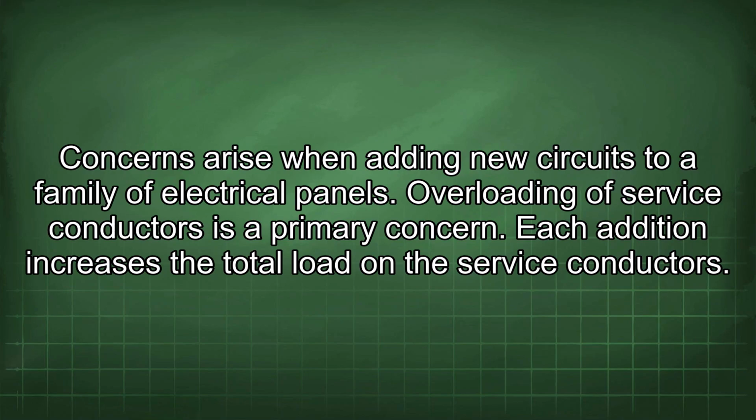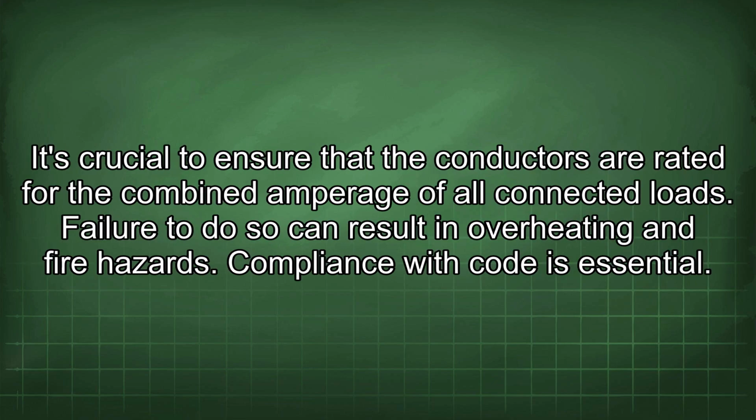Concerns arise when adding new circuits to a family of electrical panels. Overloading of service conductors is a primary concern. Each addition increases the total load on the service conductors. It's crucial to ensure that the conductors are rated for the combined amperage of all connected loads. Failure to do so can result in overheating and fire hazards. Compliance with code is essential.